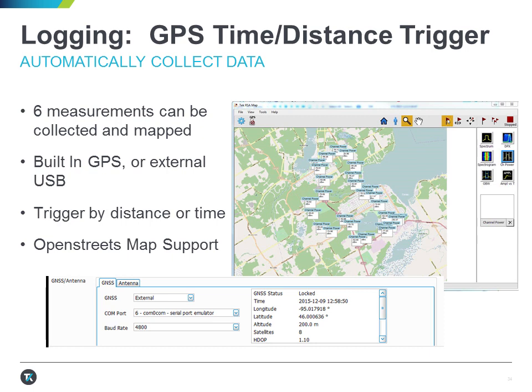With this information, we can actually create a heat map which helps us localize the source of the interfering signal. This is a lot safer and sometimes a lot faster than classic direction finding techniques because we can collect a lot of this data much more simply and then put it through a tool like Google Earth in order to map it for us.